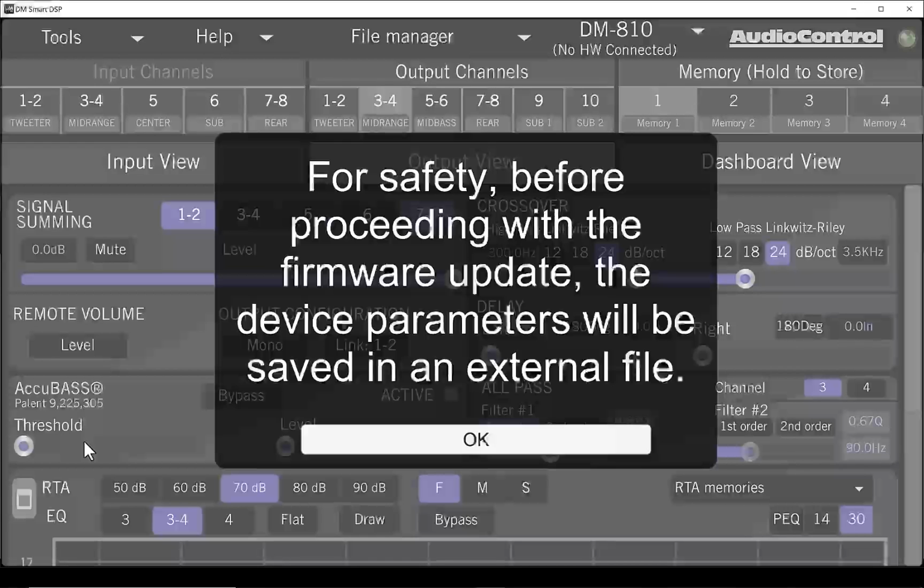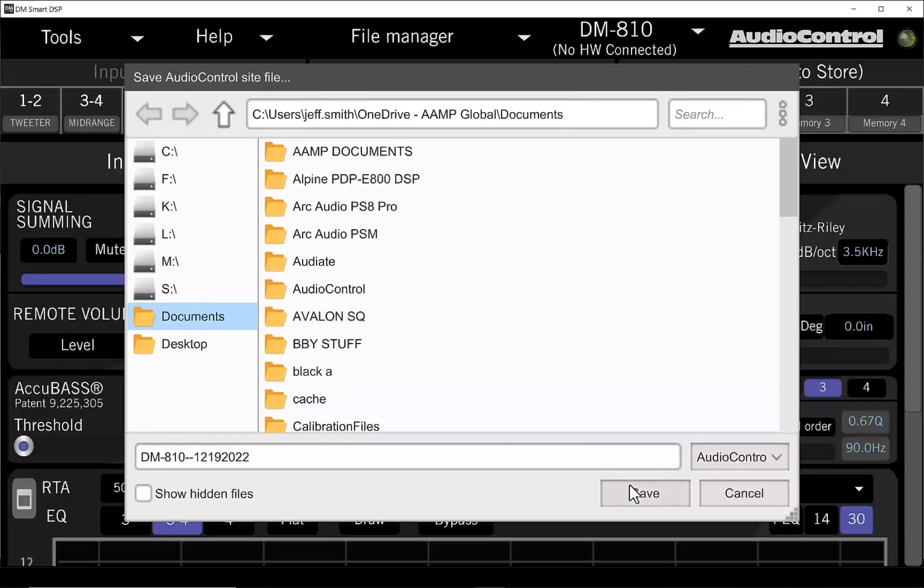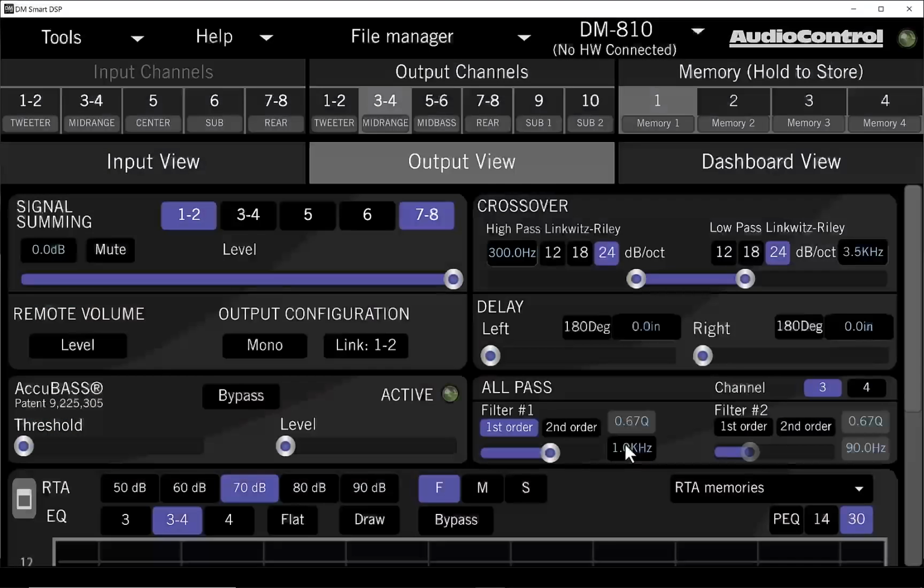Also within the Tools menu, there is an option to update the AC-BT24 firmware. This is to help alleviate many of the app connectivity issues that plague the BT24 when attempting to use it for app control or tuning. With the ever-evolving smartphone market, this should help relieve user frustration dramatically. However, I still recommend using a laptop with a USB connection whenever possible for the best and most reliable tuning experience.